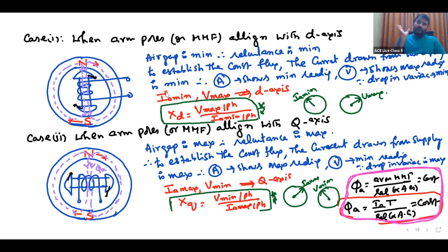It is the reactive component, because it is only magnetizing the armature core. It is producing the armature flux. That is nothing but the magnetizing current, reactive current. And you may know the magnetizing current is proportional to air gap length. In a transformer, the air gap is minimum, so the magnetizing current is less, but in an induction motor there is an air gap, so the magnetizing current is 30 to 40%. If the air gap increases still more, it will draw a large magnetizing current.